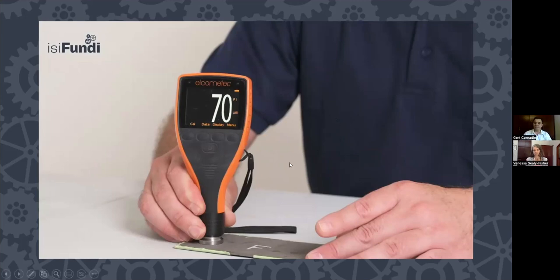But using this type of gauge that you see on the screen here, which is a method B measurement, you now have to take a representation of an entire area that you are measuring, taking quite a few different measurements and averaging those values. And there was an old method of measuring where you used to take 10 values and average all 10 values, and that's the measurement that you would have taken. And you would do this, repeat this 3 times. So that's 30 readings that you have averaged.